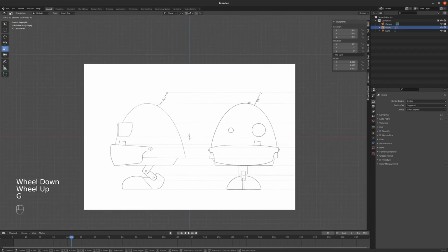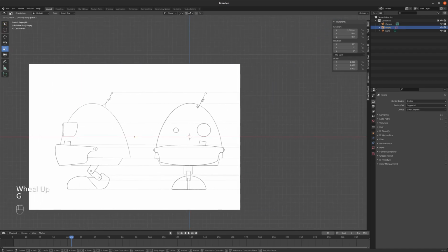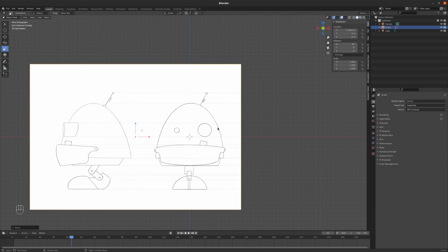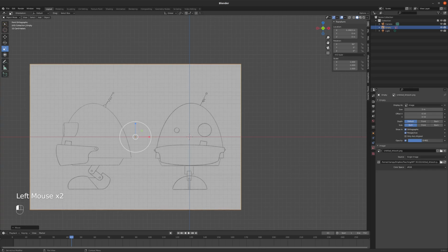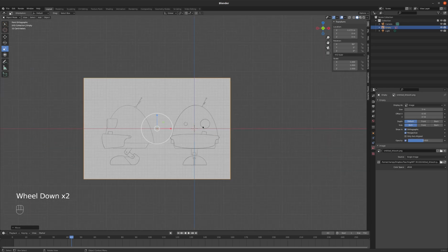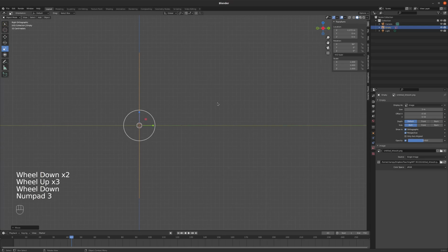And this is a front view, so I'm going to align this with the front view. And over here where I have my image attributes, I'm going to check the opacity checkbox and turn that down a little bit so that I can see my axes through this and try to align this a little bit more precisely. And I can tell that my drawing here is not symmetrical. I didn't really take the time to do that, but this works. Okay, so now let's go to a side view, and we will align the right side.